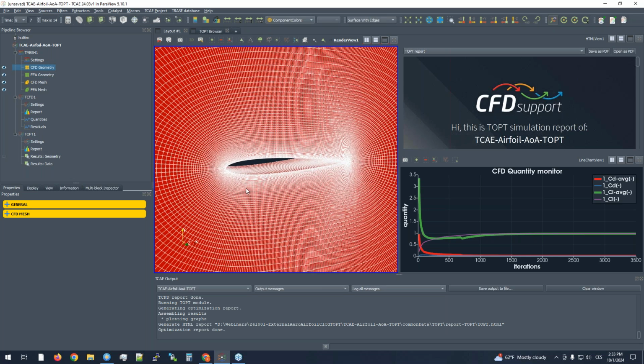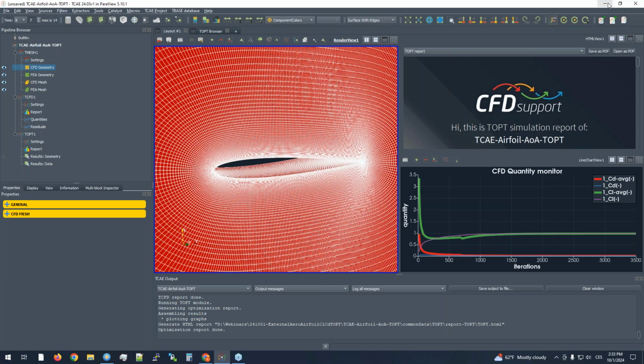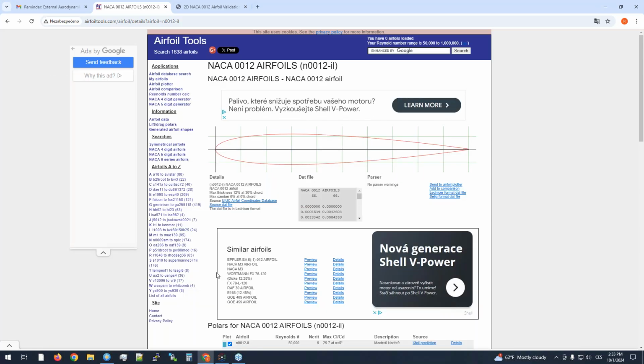workflow can be created. Okay, so how will I start? At the beginning, what I would like to do is to create a mesh from some kind of aerofoil profile. So I will take one of the easiest ones, this NACA 0012 profile. Typically you get this profile by some coordinates, and from these coordinates you need to create the geometry. From the geometry you can create the computational mesh.